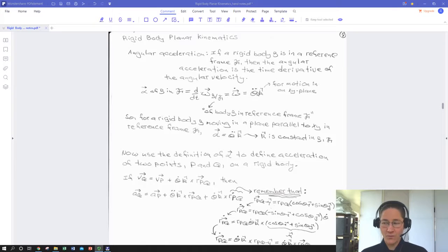And because that rigid body is rotating in plane, we're only talking about planar motion, all of our angular position, our angular velocity, and our angular acceleration are all going to have vector directions normal to the plane of motion. So we're saying that we're moving in the XY plane. So our rotational velocities and accelerations are all going to have angles in the K hat. So out of plane, planar normal. Now it could be positive or negative K hat, but it's definitely going to be in the K direction for motion in XY.